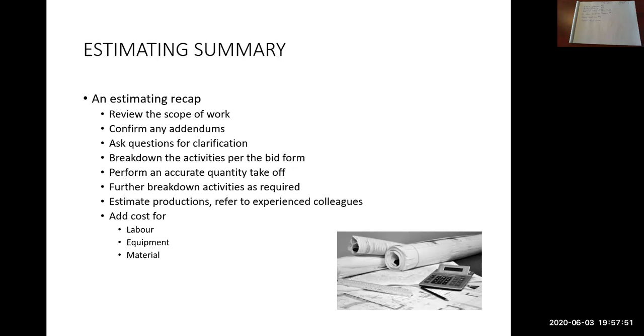So what that means is that's your work breakdown structure. So inside the maybe the utility item, so the 300 millimeter storm main item, that'll be a single line item in the tender form, you know, 1,000 meters of 300 millimeter storm pipe. But inside that bid item, you're going to break it down into things like survey layout, things that we practiced earlier in this course.